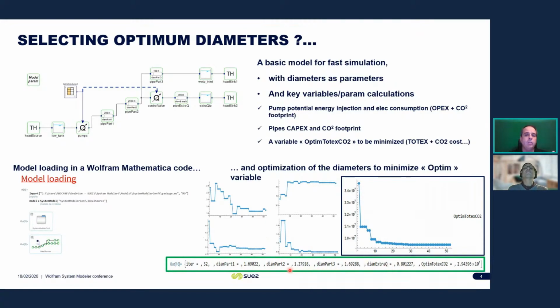The resulting optimal design is kind of obvious and at the same time interesting. The long microtunneling pipeline in this example converges to a small diameter because of the construction costs. And on the other sections, the lower differential cost converges to a larger diameter to reduce energy consumption. So it finds the balance in an expected way on this example. Moving forward.